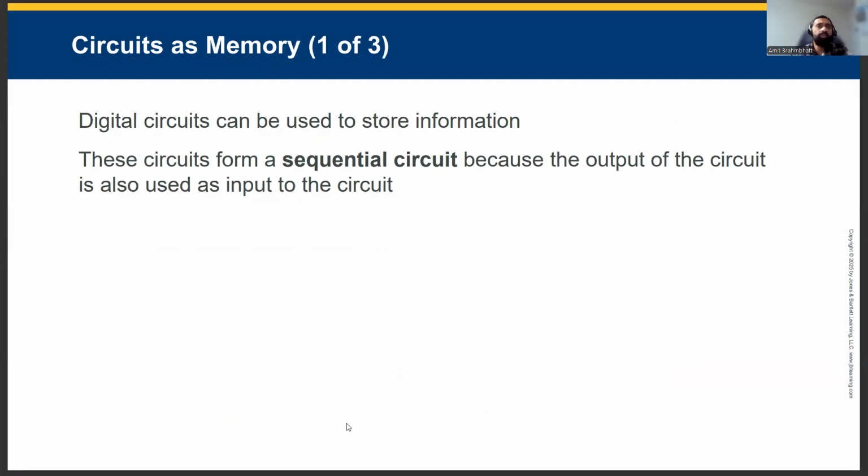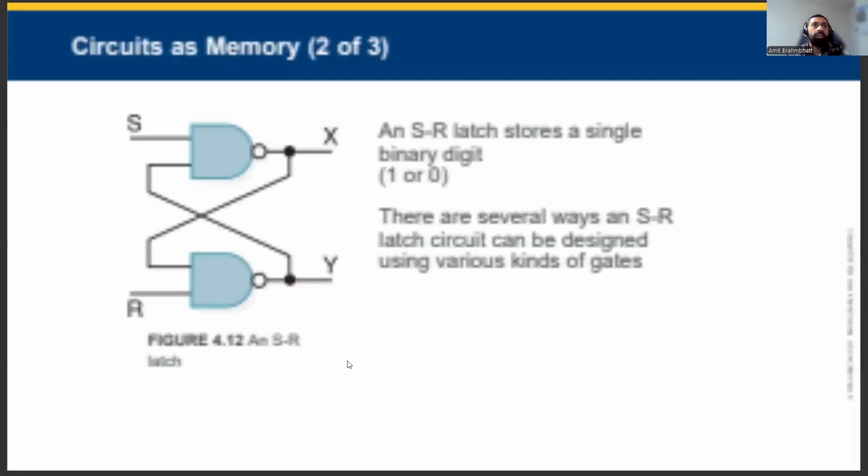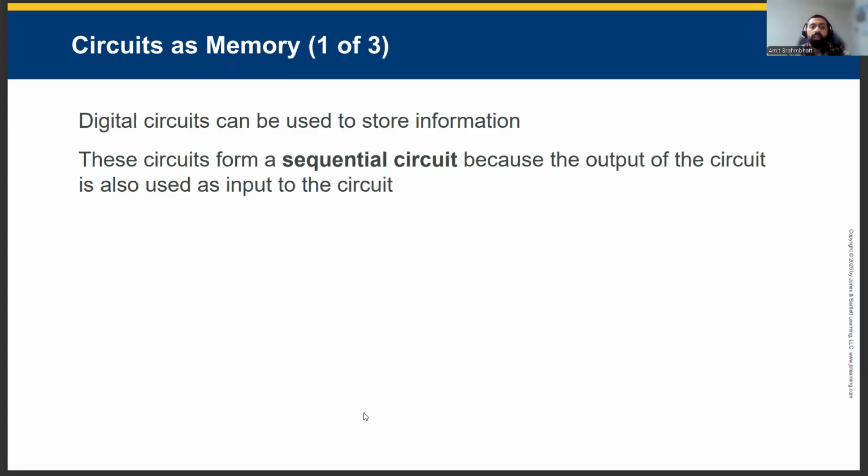Circuits can also remember. When outputs are fed back into inputs, we form sequential logic that stores state. This memory allows systems to count, hold configuration bits, and synchronize operations across cycles. The simplest memory element we'll study is the SR latch.